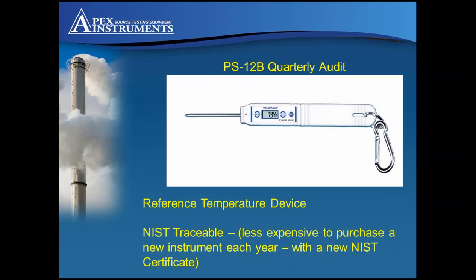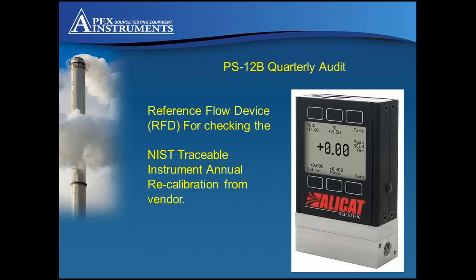However, we've found it's actually less expensive just to replace the thermometer every year than it is to send it in, because the recertification of the thermometer is actually more expensive than purchasing a new one. The reference flow device is a mass flow device that we use for verifying the dry gas meters. Again, this needs to be recalibrated annually by the vendor.